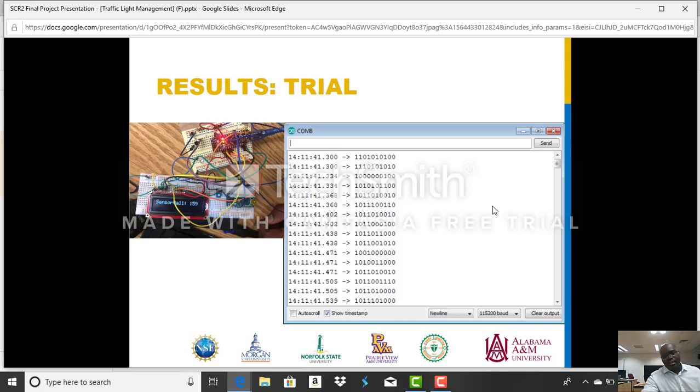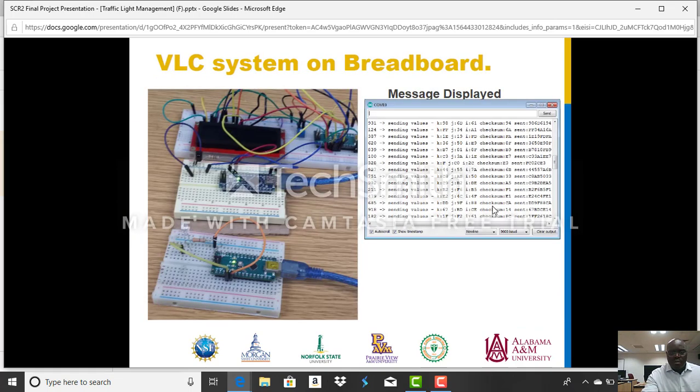So we went back and disconnected the whole testbed, and instead of using the ordinary LED, we used the IR LED, and we had a new IR receiver and a new sketch that had Manchester encoding in it. And when we set up the testbed, with the emitter side and the receiving side next to one another, we were able to receive data and display it on our LCD. So we are actually getting the exact data that we're emitting from the emitter side.